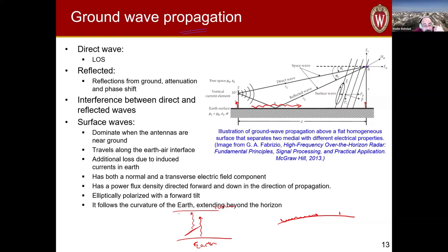because your wave would not be reflected if you have vertical polarization. But if you want to have a vertically polarized wave generated by, let's say, a dipole antenna, vertical towards the ionosphere, then that becomes a little bit challenging because my dipole antennas have nulls.